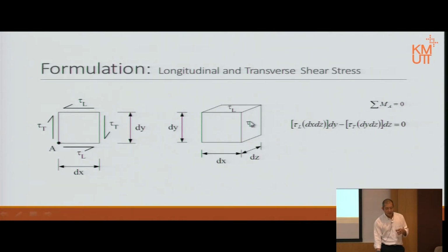The second term is that caused by that stress, working sideways. So it becomes tau T times the area. The area is the height times the depth. The height is dy, the depth is dz, dy dz. And then the arm is dx. My apology, that one has to be dx. Then it must be 0. I will change it in the sheet.